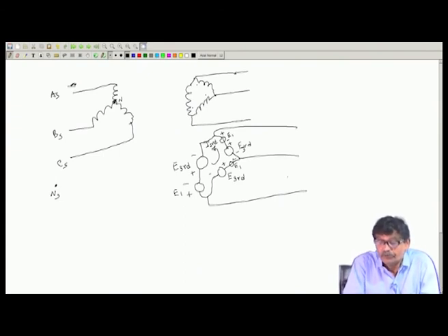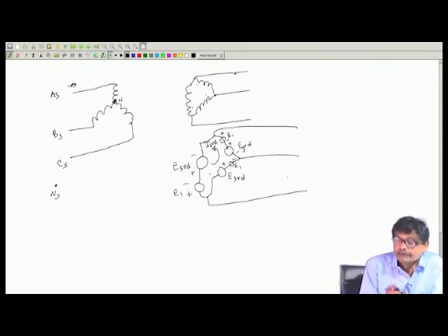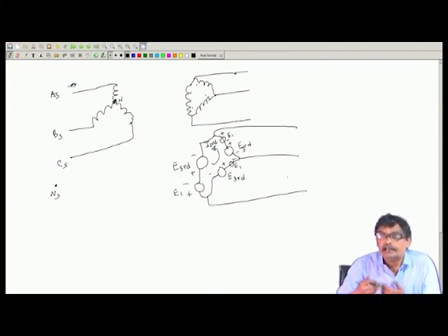But now, if you look at the operation of the transformer, I will say that the fundamental component of the magnetizing current will come from AS, BS, CS, and the third harmonic exciting current which is needed, the transformer will self correct it by circulating a third harmonic current here.